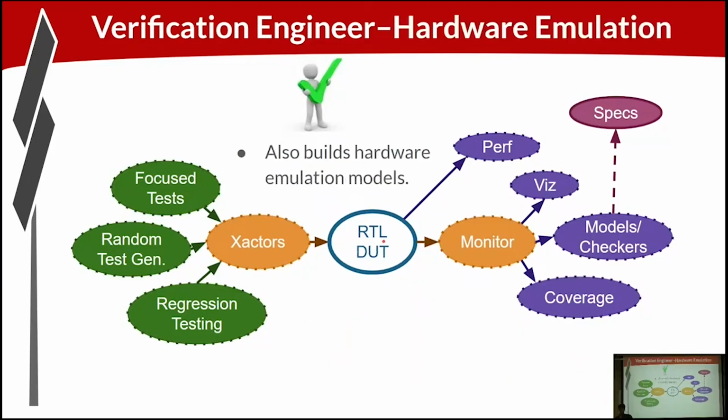When you're doing hardware emulation, you're really trying to hit those deep simulation cases. So it might take days of simulation to get through just hardware reset alone on a full chip system. So you might use the hardware emulation platform to do the reset sequence. You might use it to do Linux boot, for example.